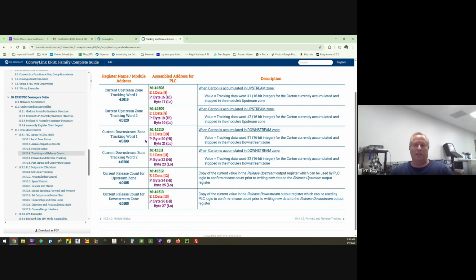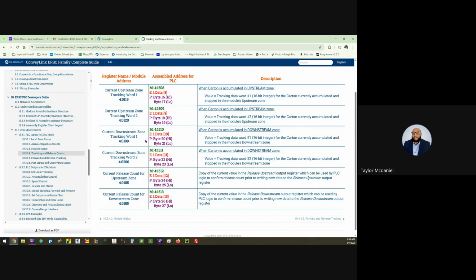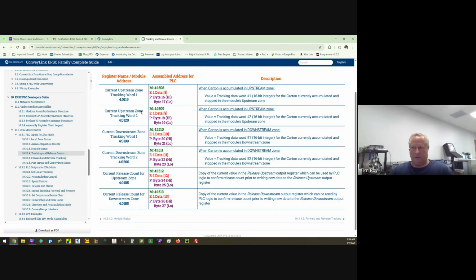Okay. The crazy thing is when I teach how to do tracking and write the tracking data, I take the DINT apart into two integers, which means for ease, I should have just left it as two integers. I guess this was something that really wasn't thought out in the very beginning. And unfortunately, because I have just continued it, it's kind of the way it is. But knowing that, it's just a couple of instructions in Allen Bradley. So it's two separate words. Yes.